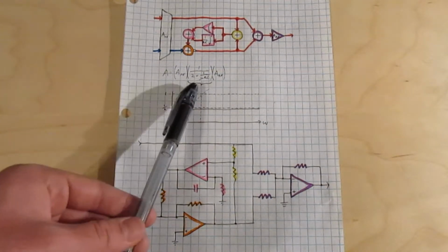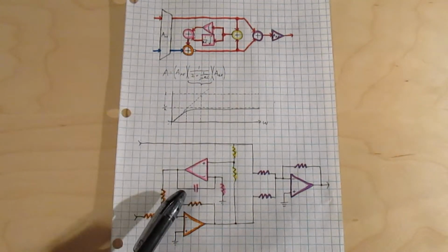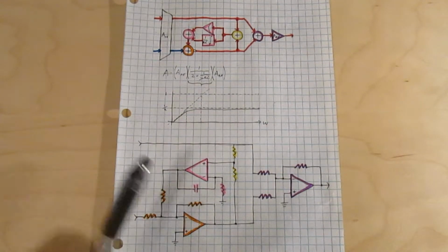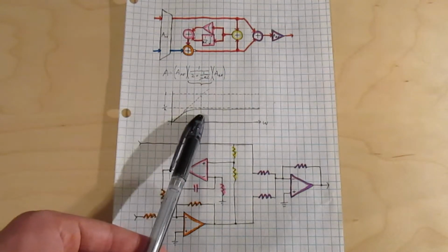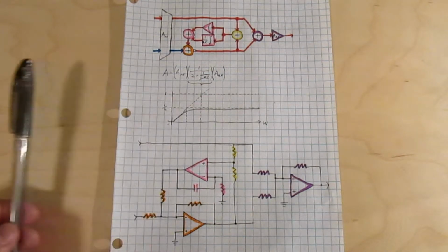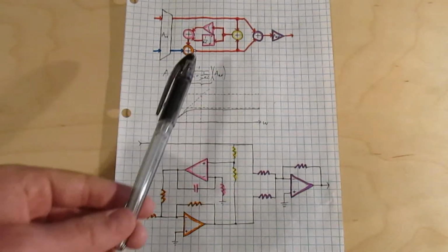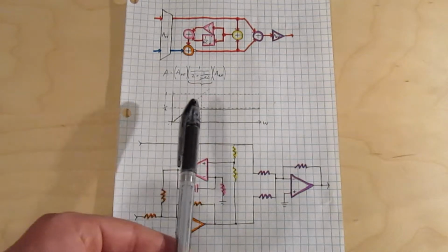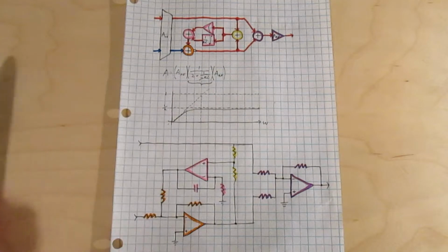But the way you normally do that is by having a really large resistor and capacitor in the circuit. And the resistor and capacitor in this circuit are already 100 kiloohms and 1 microfarad, which are already pretty big. But here we can get the corner frequency even lower, basically for free, without having to change the resistor and capacitor at all. So not only do I want to not have any gain reduction from the DC offset tracking, but I also want to be able to do something similar and push the corner frequency down even lower.